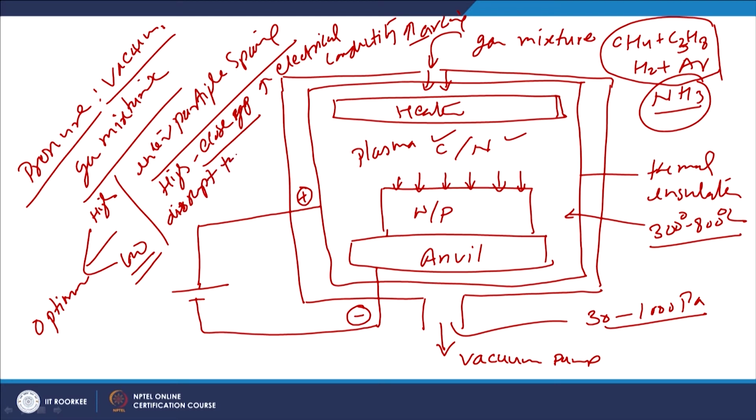the discharge or plasma formation process. And so it is neither good to have the higher pressure within the chamber, nor is it good to have the low pressure within the chamber, because in either case it will be leading to problems in terms of arcing for high pressure and disruption of the plasma formation under low pressure conditions. So now if we see the typical plasma